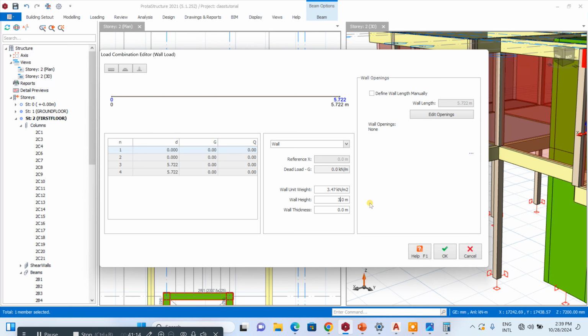So there you reduce, your roof trusses will actually rest on there. So this one, they are actually not load bearing beams. They're just for helping to reduce the partition, so that you don't begin to have your roof trying to buckle or sink.